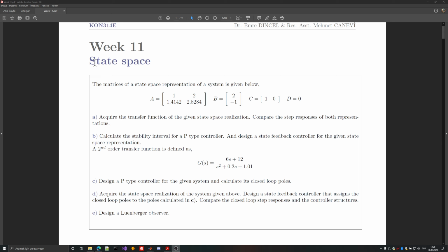So if you convert the state space model to the transfer function, the reason that you have only one single possible way to do this is because there's only one relation between input and output. But if you have a transfer function and you're converting that into a state space model, then the internals may change.